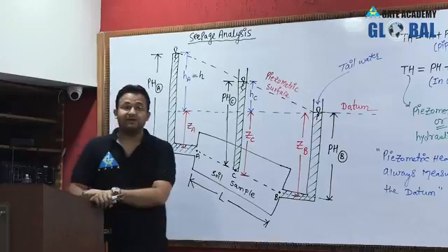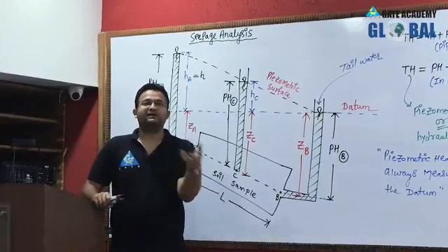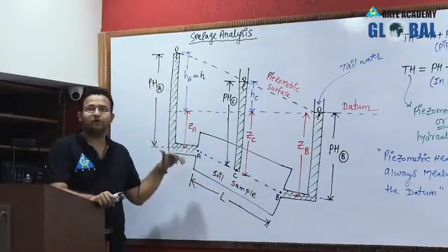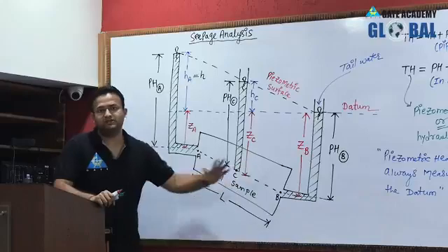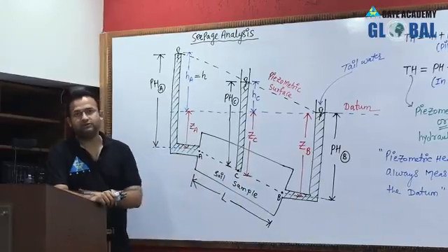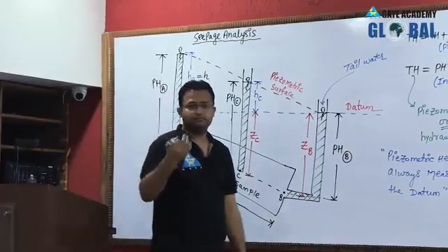I always consider the worst condition. Which point is under the critical condition? Point B, point C or point A? Of course point A, because it is subjected to higher seepage pressure. So this is the dangerous condition, this is the dangerous point. So I should give the answer at A, that's it.